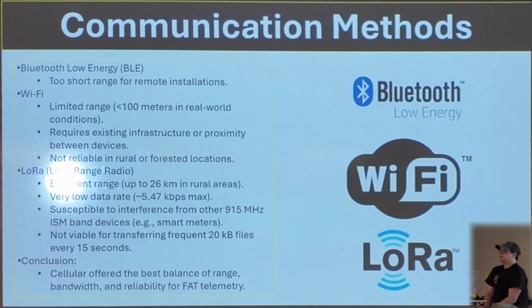I considered several different communication methods. I looked at using Bluetooth Low Energy or Wi-Fi, but these were simply too short range for remote installations. It could have been possible with additional infrastructure, like if you had an area where you could install, say, a Wi-Fi router that everything talks to. But this would require additional installation in the field versus something that could just run at the deployment itself.